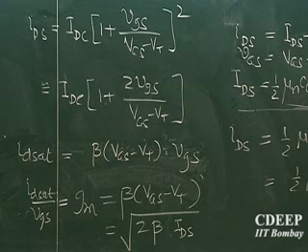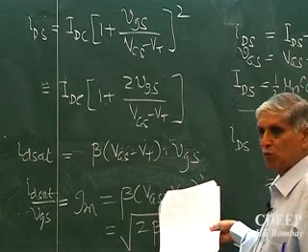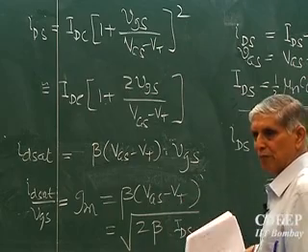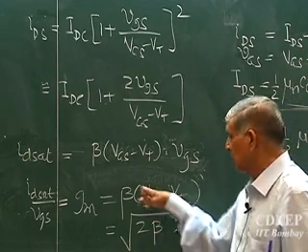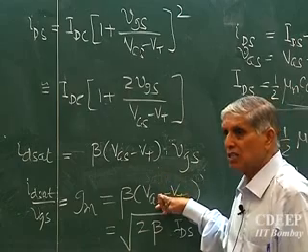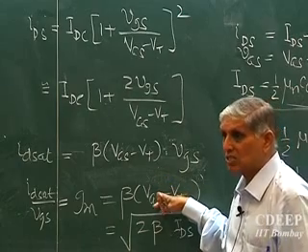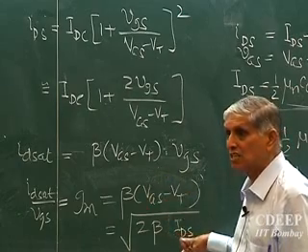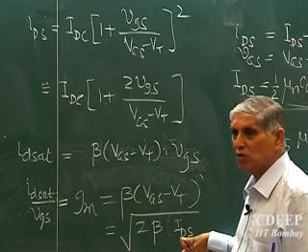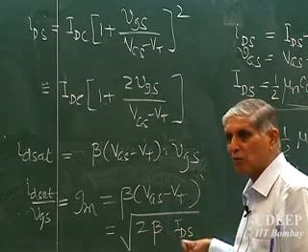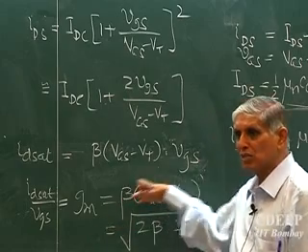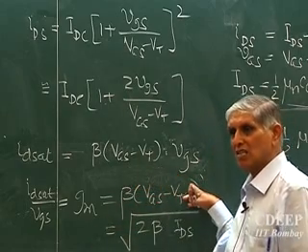So why is this equation necessary and not this? What is the difference between the two? They are the same, but why did I show you both? What does this mean? DC biasing using resistors. This is voltage biasing. This is current biasing. If I am doing current biasing, I can directly find my GM. If I am doing DC voltage biasing, I can still find my GM.